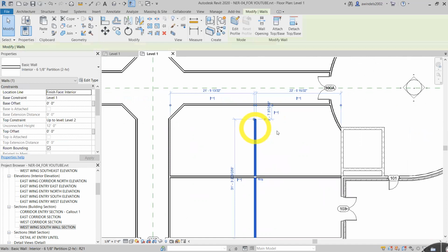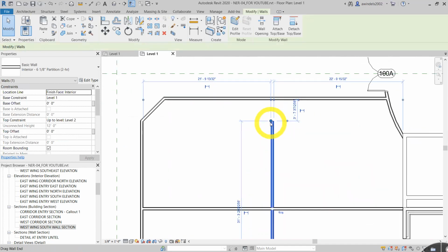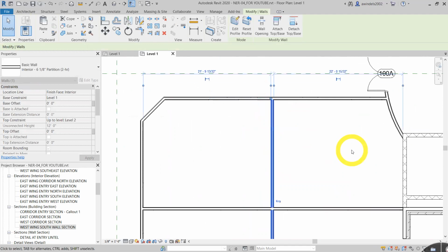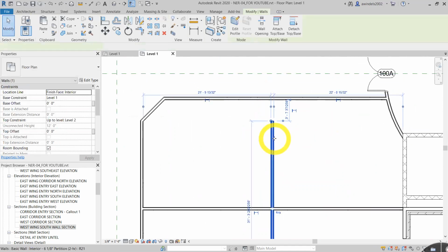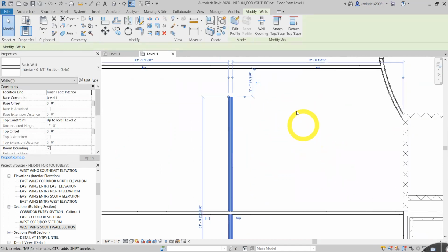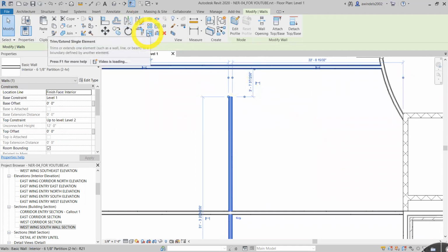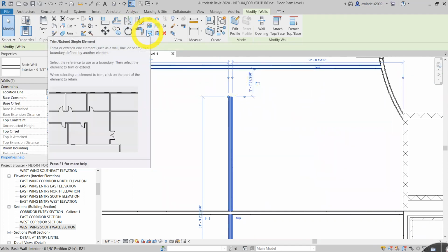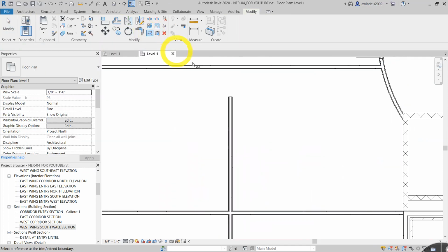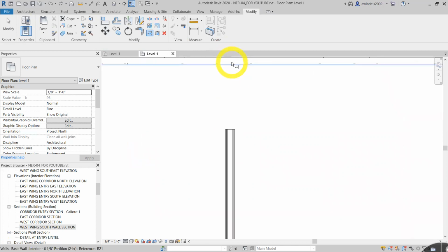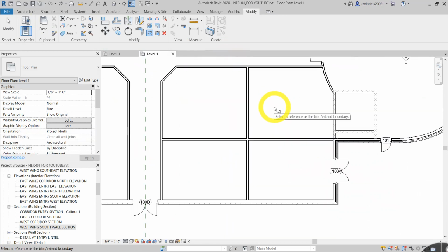We're going to do it differently up here. For example, you can drag right into the wall to extend right to the center of the wall, right? That's probably easier for a lot of you and myself, but I'm going to click this wall. We'll use the trim extend command more surgically, like if we want to go to an exact spot. Pick the same command, but we're going to do a different purpose. We're going to say the trim or extend boundary. I want the extend boundary to be, probably doesn't matter too much, but let's pick this lower edge right here. Then I'll pick what I want to extend. There we go. So that's it on those commands.